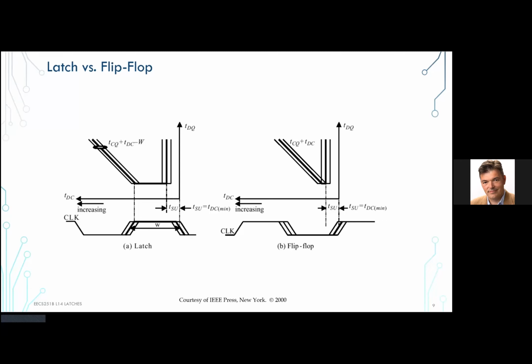The concept of this that we'll see a little bit later in the next lecture one more time is that when using latches, I don't have to account for the impact of jitter or the skew if the data is arriving over here. These three graphs are showing that the whole thing is moving with respect to the clock, skew or even jitter.